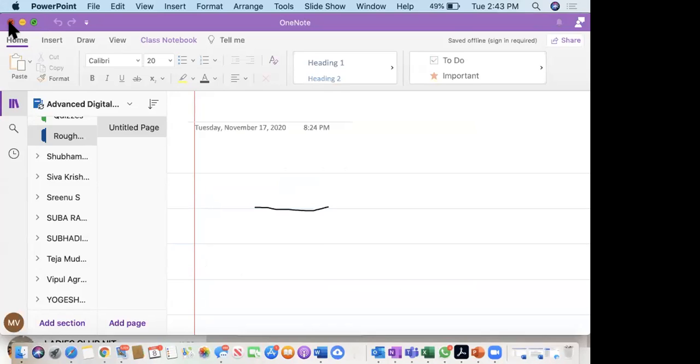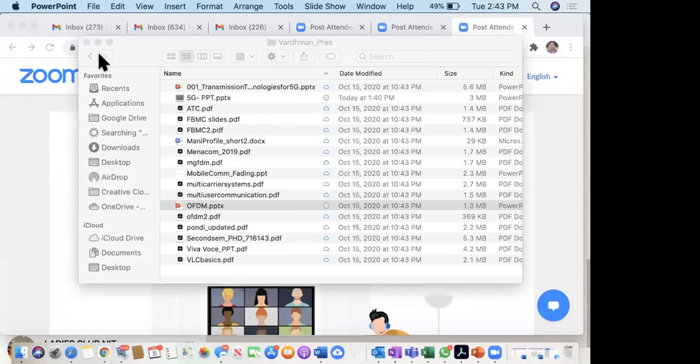Good afternoon, ma'am. Is the size of the IFFT and the number of subcarriers required to be the same, ma'am? Yes, they need to be the same because you are using an N-point FFT. In the N-point FFT, suppose you take n equal to 0 to n minus 1, you use your X of n, that is your data symbols, and e power j 2 pi f t, which you have to translate into the digital domain.